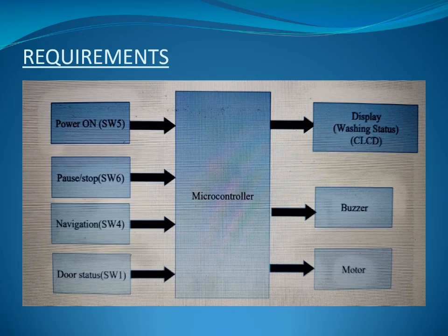The third one is the water level screen. Here also we have used SW4 as the input. Using the keypad SW4, we can scroll between the options available. A long press of SW4 will select the option highlighted with an asterisk. The options here are auto, low, medium, high and max.